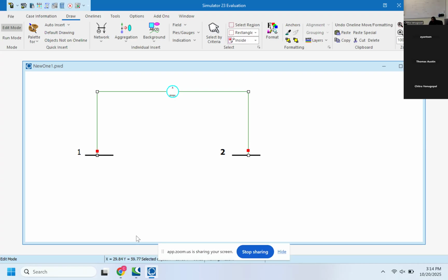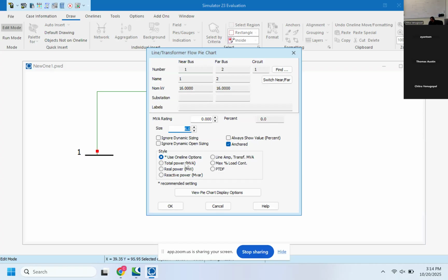Right. Now the blue bubble here is showing you the line parameter when the whole system is running, what the line capacity is. So now you can double click to open and you can see. What do you want to see in the line? 0.3 and 0.6. When you double click to open this, you can select what you want to see: the apparent power, real power, or reactive power. You can select whatever you want, or you can see the current.